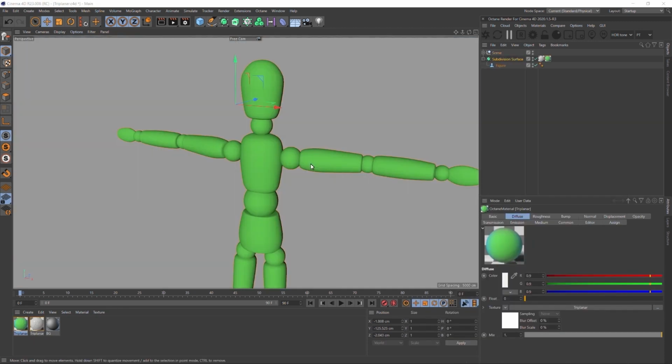All right, so sometimes you've tried all the other methods that I have mentioned, which are not even close to all the ones available to you, but just the ones that we have time to discuss. And you really just can't get that model cleaned up enough, or you have too much curvature on it. You can't pull a good untriangulate on it. You can't or don't have time to do a UV unwrap on this to lay textures across this properly. So let me talk about triplanar textures and why they're important.